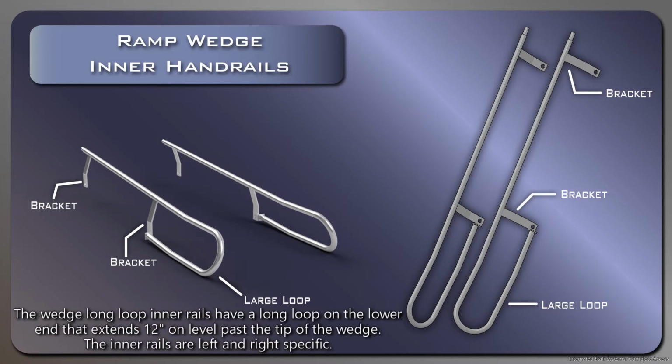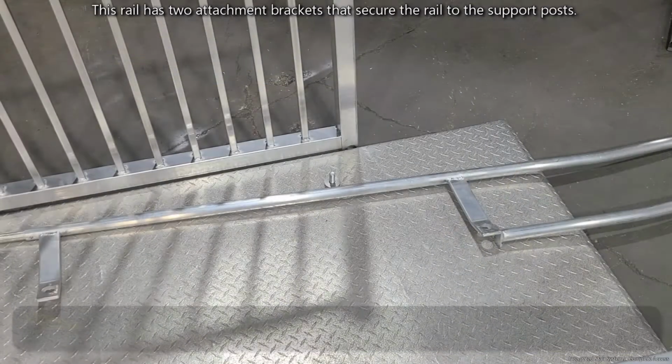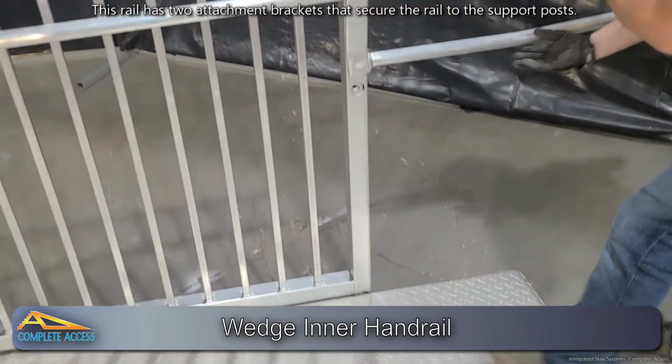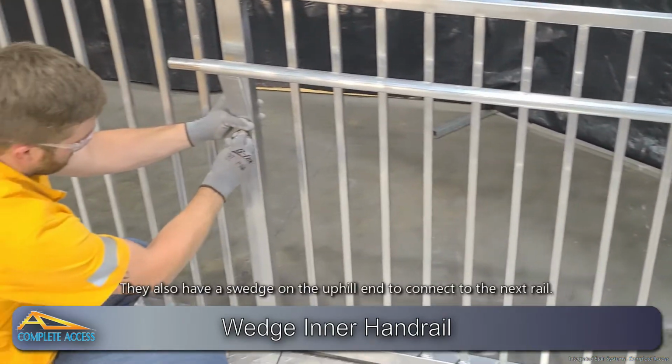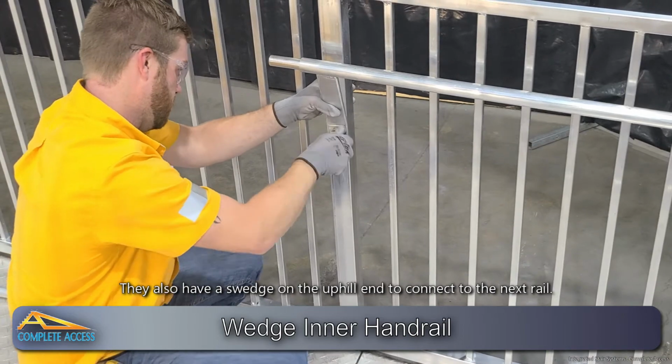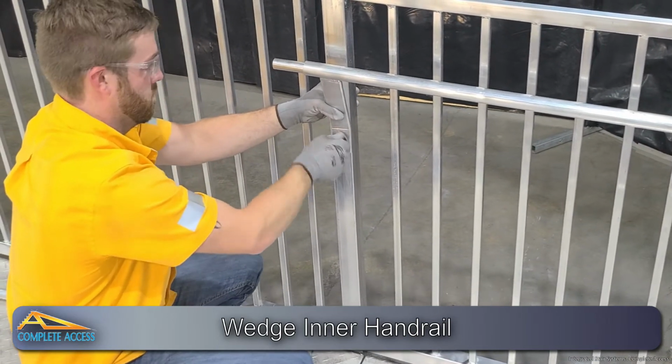The wedge long loop inner rails have a long loop on the lower end that extends 12 inches on level past the tip of the wedge. Inner rails are left and right specific. This rail has 2 attachment brackets that secure the rail to the tops of the legs through the picket guards. They also have a swedge on the uphill end to connect to the next rail.